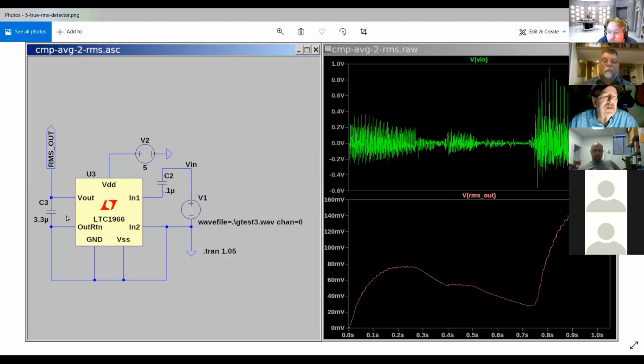And incidentally, the people who design, whether it's an analog processor or the fancy digital stuff that's emulating RMS, have got to do some very fancy things to work around the fact that the capacitor size sets your time constant, which with RMS sets your averaging constant.